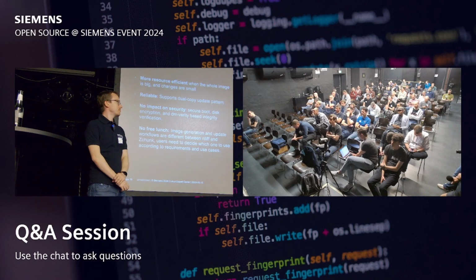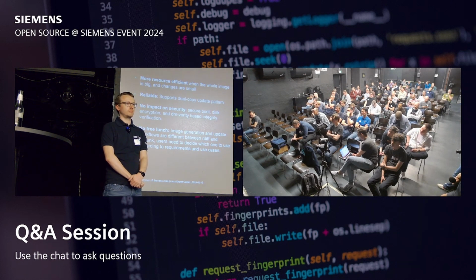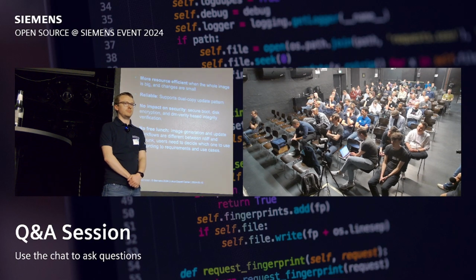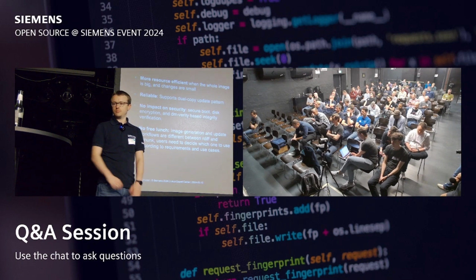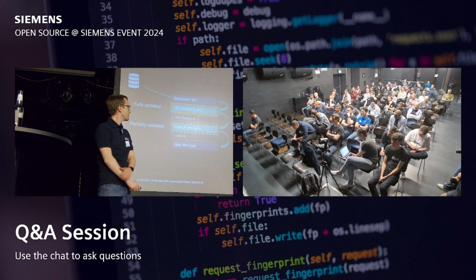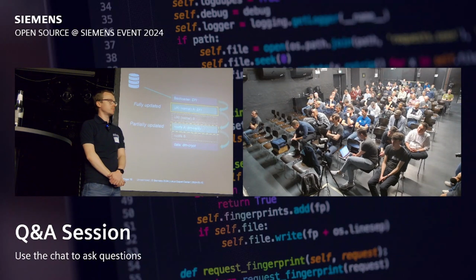The rollback contains, besides the rollback of the core images that we have shown here, which is the easy part, at least from a distance perspective, the rollback of your own state. And that's normally the case which is not tested. Now you do maybe the forward update of your device state and test this heavily, and then you forget about what if this goes wrong and I go back? Then I'm with the new data, with the old image, and now I'm stuck. And now you have a service case in the field. That is not that easy to achieve.